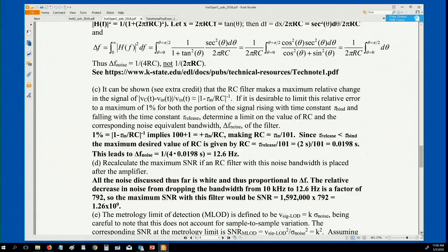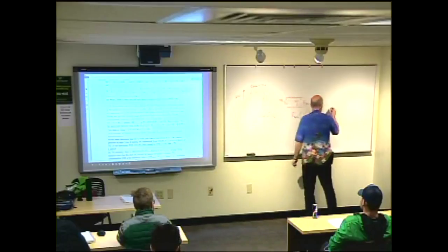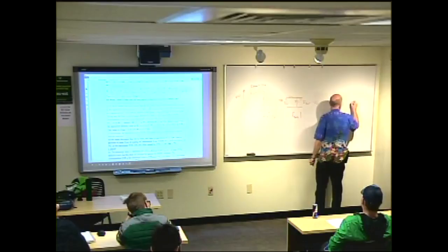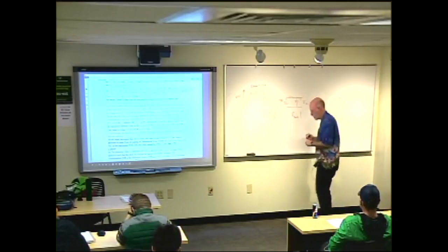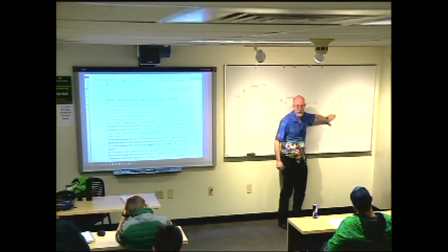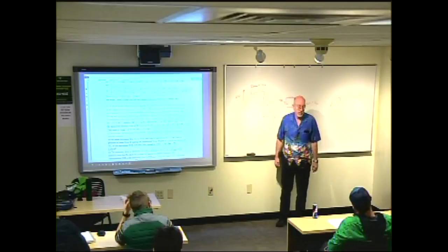So you guys have seen, I hope, a square wave put on an RC filter before, and you've seen what it does at the output. If I put a square wave in, I get something that rises and then falls and then rises and falls. Okay. And so it's clearly messing up a square wave. The filter is clearly distorting the square wave. Will it distort this? Well, it depends on how close it is to a square wave.